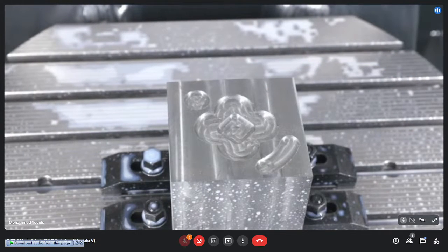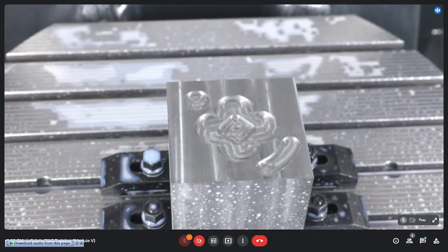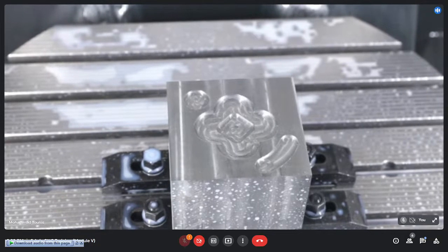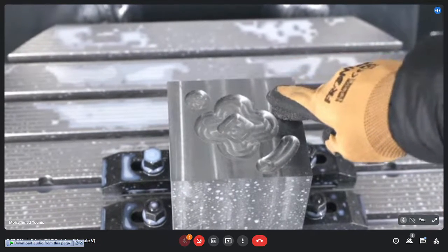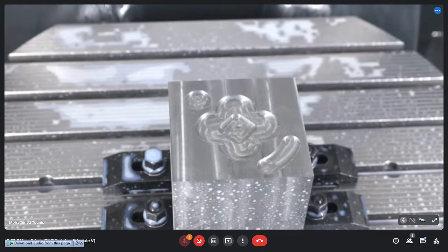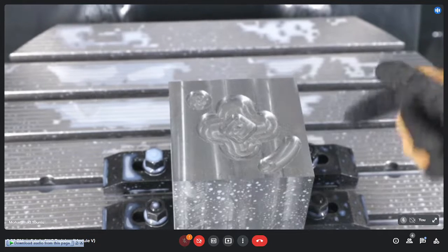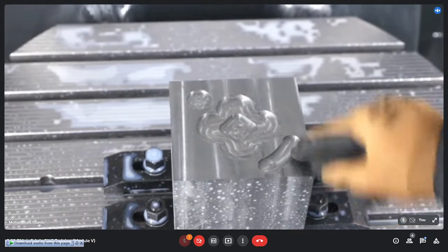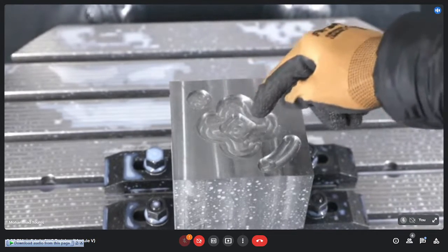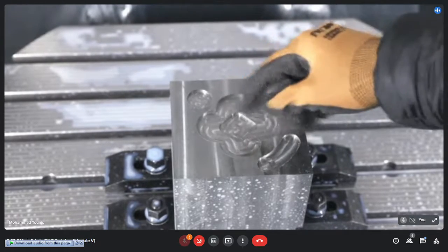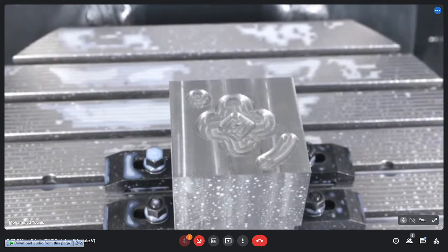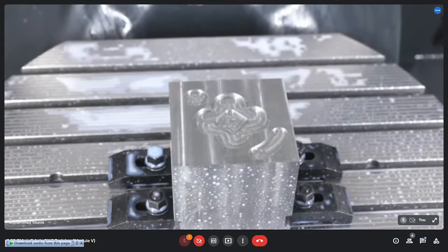But if we are going to do it manually, I mean, if I'm going to write a complete code for this contour, then the program will be very lengthy and very complicated, because while writing it manually, I have to write a code for this movement, this extreme movement first. Then again, I have to write a code for the step over of the tool. Likewise, I have to see how many step overs will be there. So the program will be lengthy.